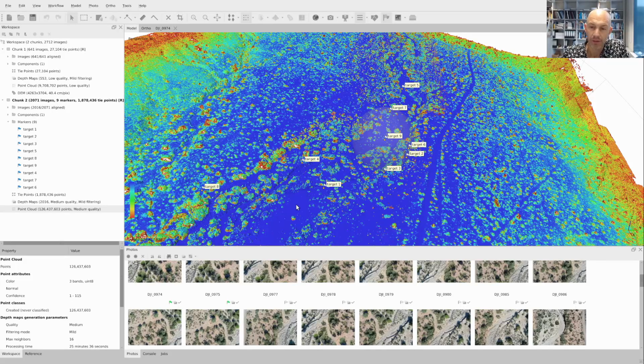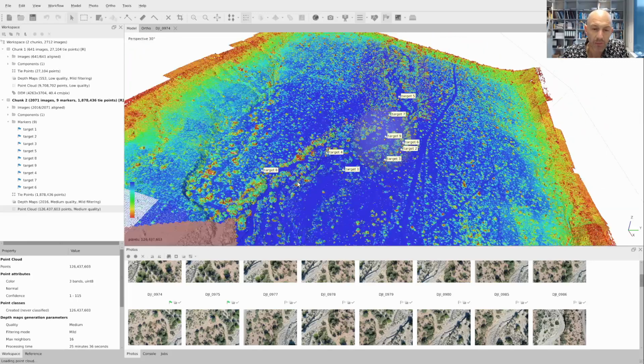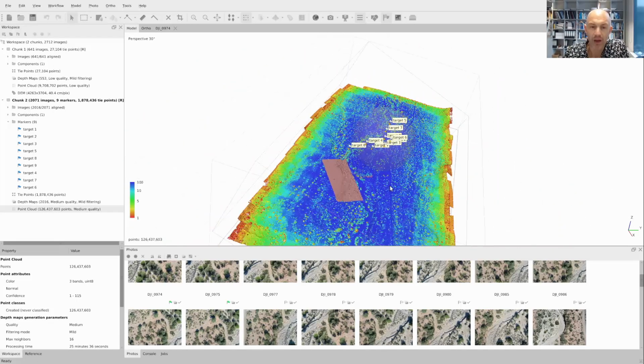This means that this is a high quality point because it has been identified on many photos. The reddish and greenish colors have a somewhat lower quality, and most of the times these colors are related to vegetation, because vegetation is then only seen from a few photos, or at the borders of the scene you have a lower number because you have fewer photos taken, therefore you have less overlap, and therefore you have fewer scenes.